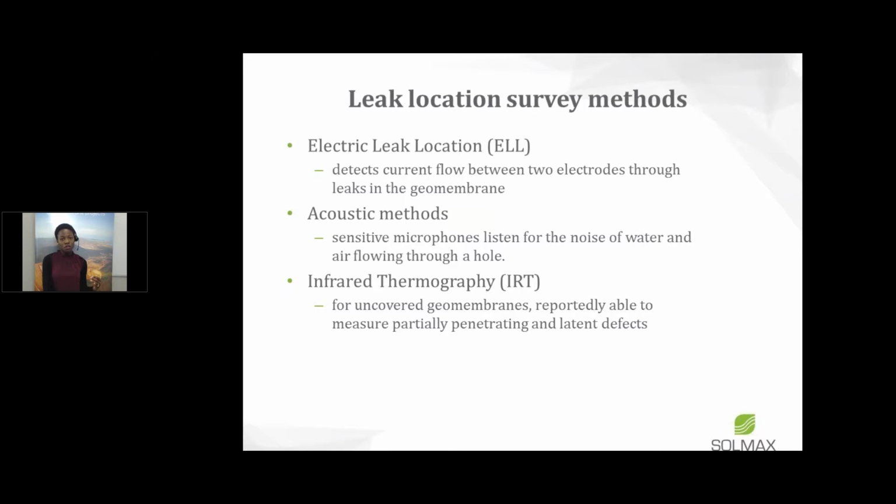The acoustic method utilizes some special microphones, and they can detect the noise of water or the flow of air through a hole. The infrared thermography method is for uncovered geomembranes, and it's been reported by the sites that offer the services that they can detect latent and partially penetrating defects.